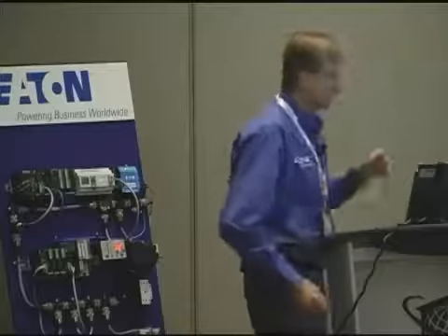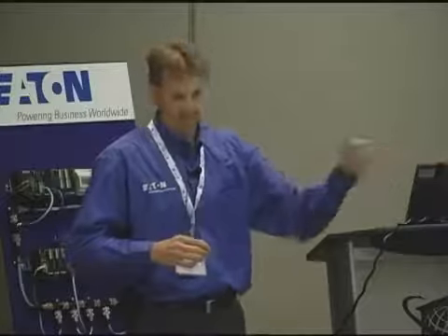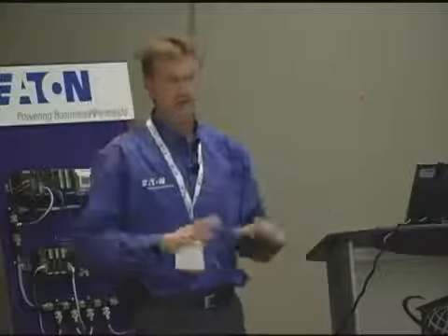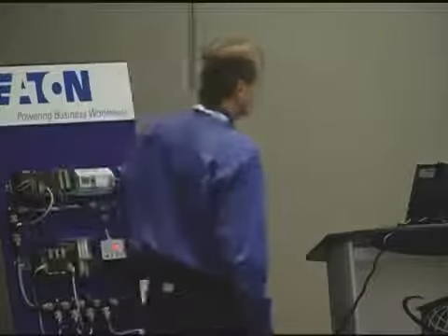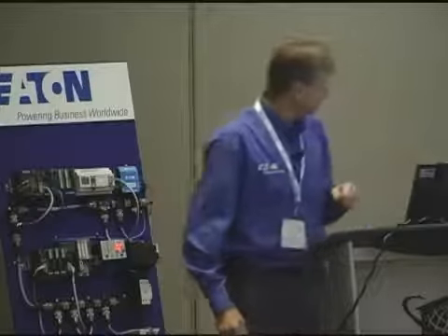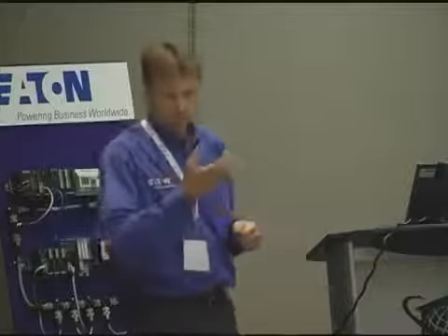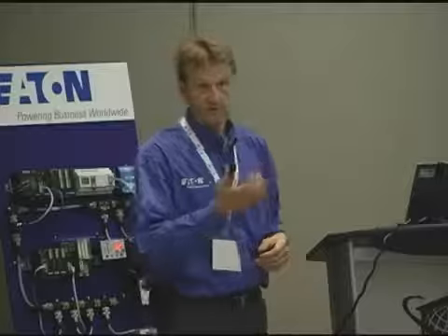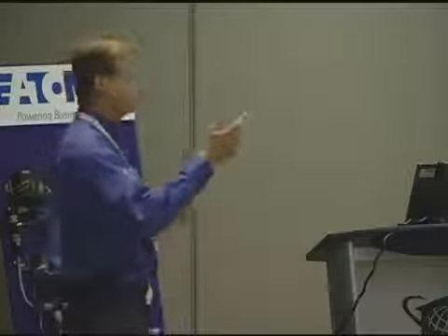We can do broadcast messages. That means we can send out a message that goes to everybody, all the slaves. Because typically you would go, I'm a master, I'm going to send a request, I want this information from you, and I want that back. But you can also do a broadcast that says, everybody do this. That's a broadcast message. You can have up to 247 slave nodes, and a little sub-note, 32 devices without a repeater. A repeater is a way to boost your communication signal. So it extends your network length.